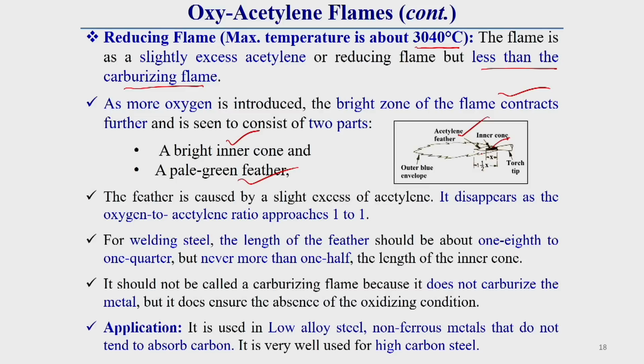This feather disappears as the oxygen to acetylene ratio approaches 1:1, because as more oxygen is added to this mixture, the feather gradually decreases and it vanishes once the ratio becomes 1:1. That means the oxygen to acetylene ratio becomes 1:1.